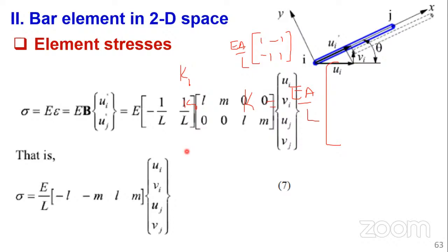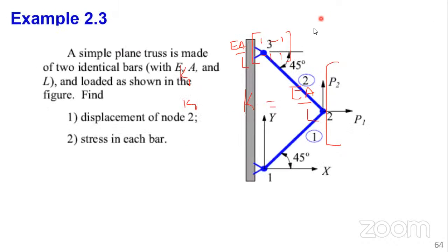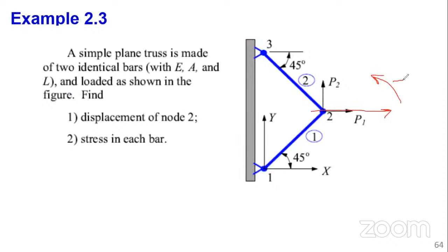So what do we need to do to get the direction cosines? We need to get this angle. And to get the angles, we get the orientation. And this is how we read angles. The horizontal x-axis, counterclockwise, that is positive. That's how we read them.